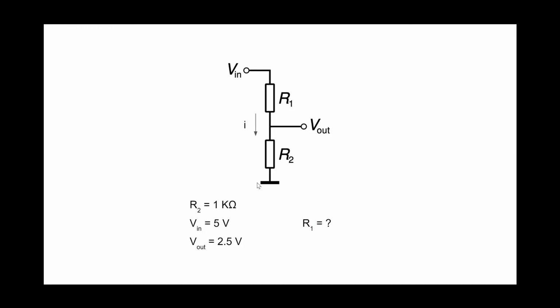Now, what value would you read if you connect Vout to Arduino in the voltage divider? First of all, since we put the voltage Vin on the circuit, let's say the current I flows, then Vin decreases subsequently across R1 and R2.